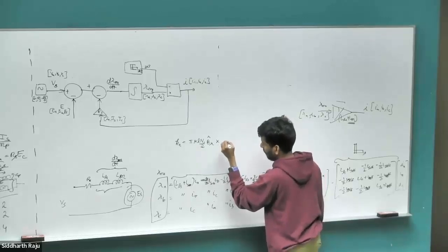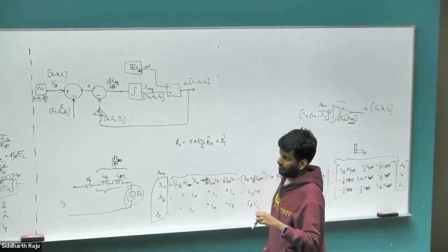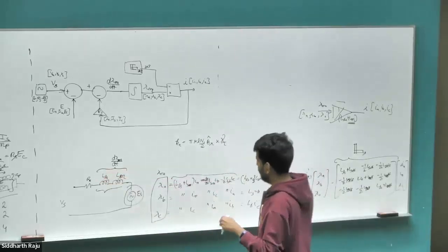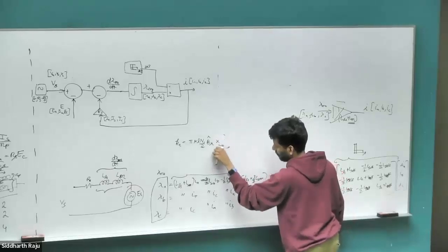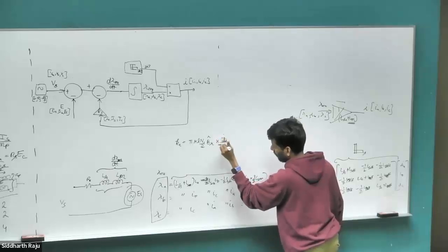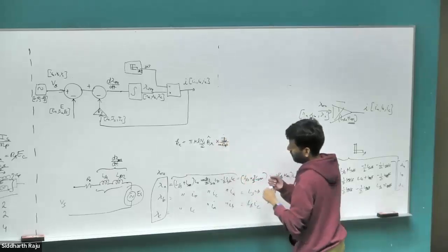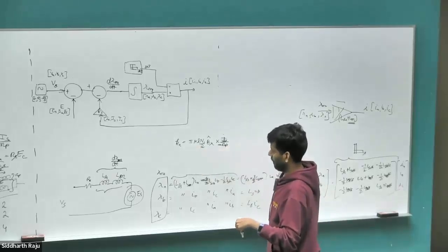Let's call it gamma tau, which is basically just going to be the number of series connected coils. Maybe I can just replace that with the inverse of the number of parallel connected coils, because the current is going to split across these coils, so the NP factor gets introduced.